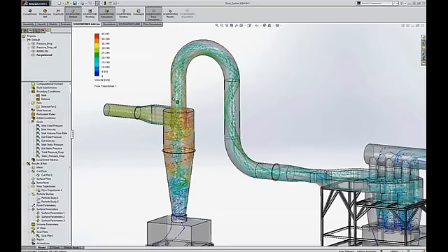Question is, so weldments are best done using beam analysis? So yes, because typically weldments are long and thin, and so they lend themselves to being represented as beams. If you do a hand calculation on a beam, it's sigma equals My on I plus the axial load. So it's the simple bending moments and axial and shear forces that you use to work out the stress analysis, and that's what you do with the beam element analysis.